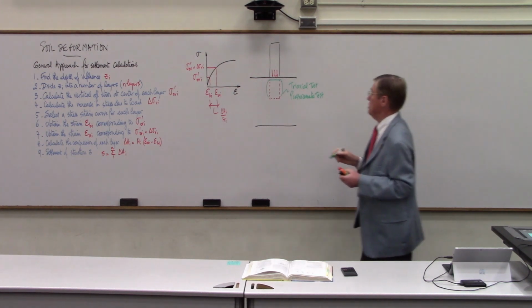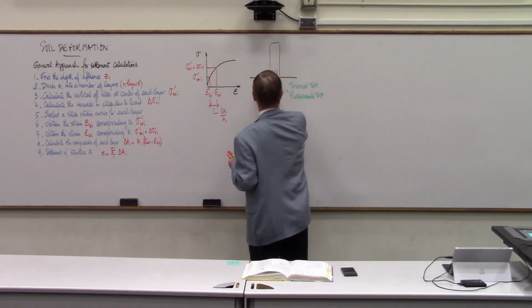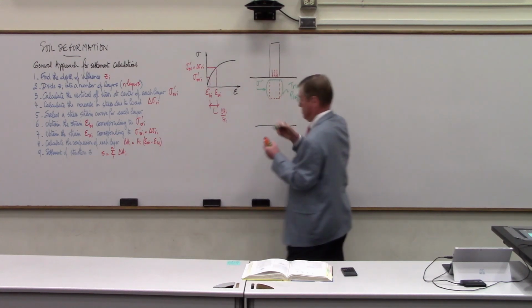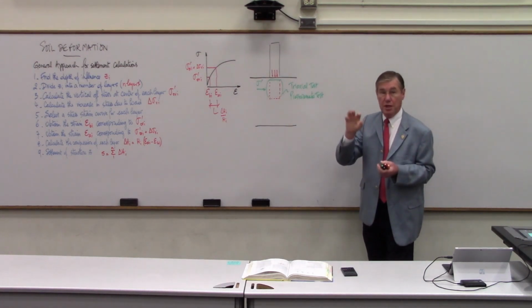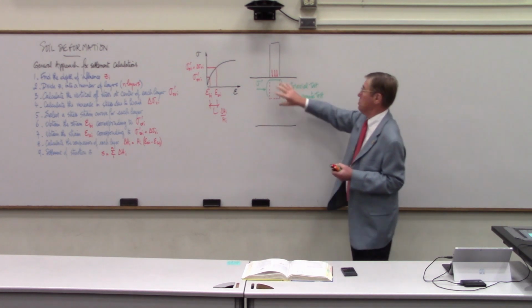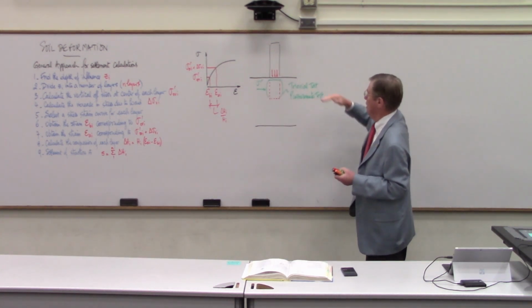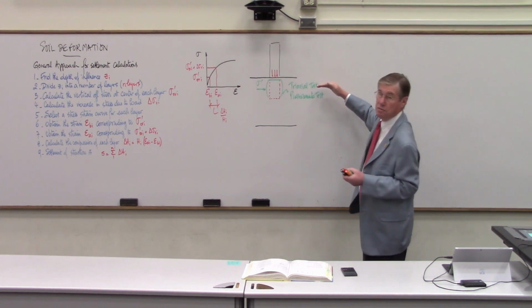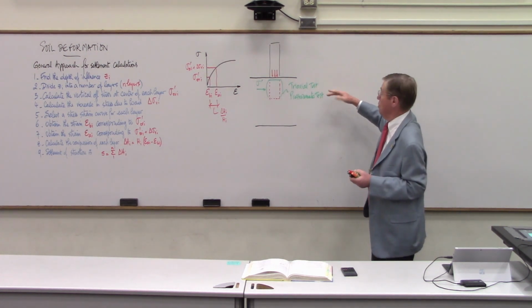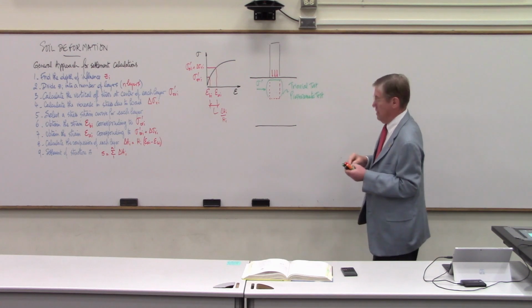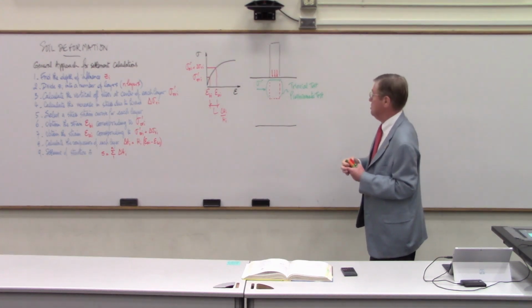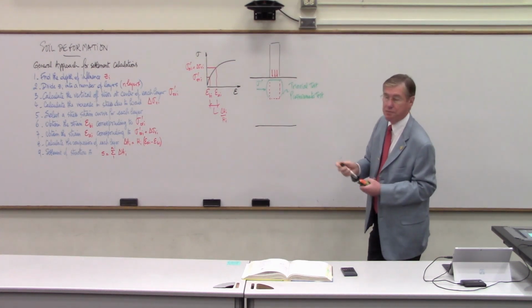And of course, you would want to look at things that would correspond to the stress level associated with that particular deformation process. But in this case, a stress strain curve associated with a well-selected triaxial test, and a pressure meter test would make sense to me.